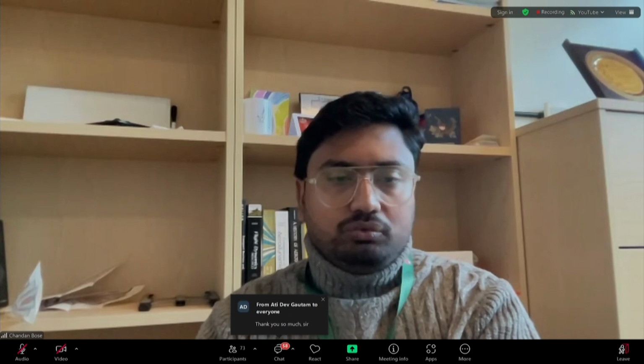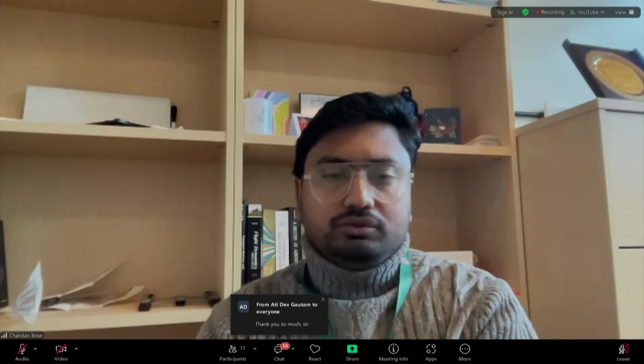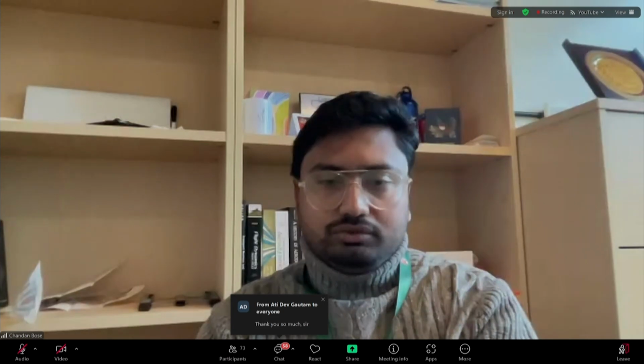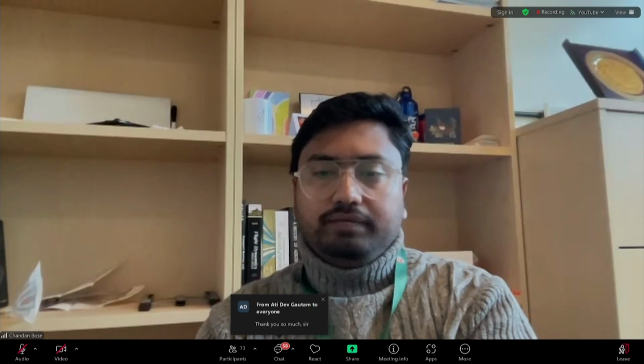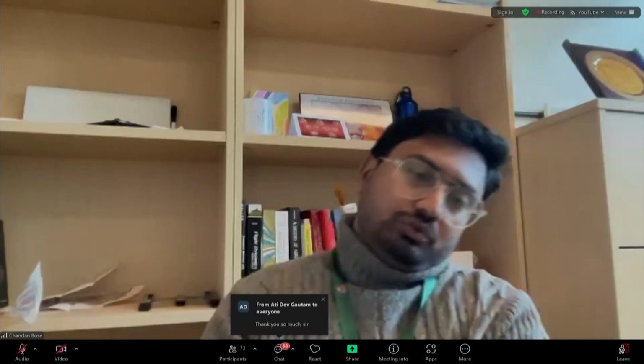Okay. How to implement an appropriate momentum source term in the Navier-Stokes equation? For that, you need to rebuild the solver, modify the source code of the solver, and recompile it. I think I have some tutorials on my YouTube channel, but again, we don't have time to demonstrate how to do that now.